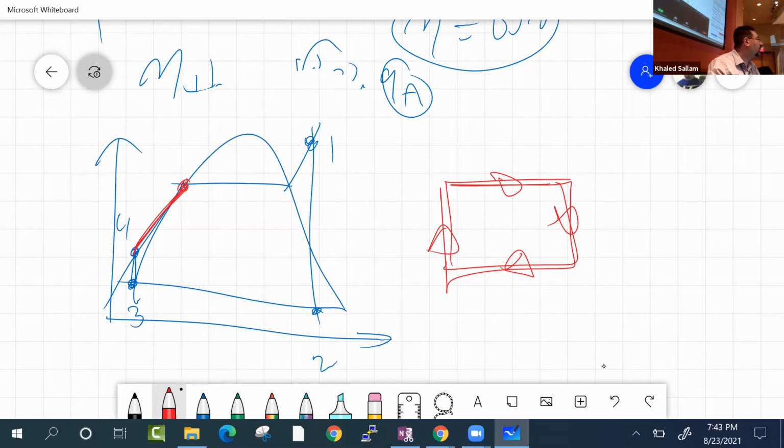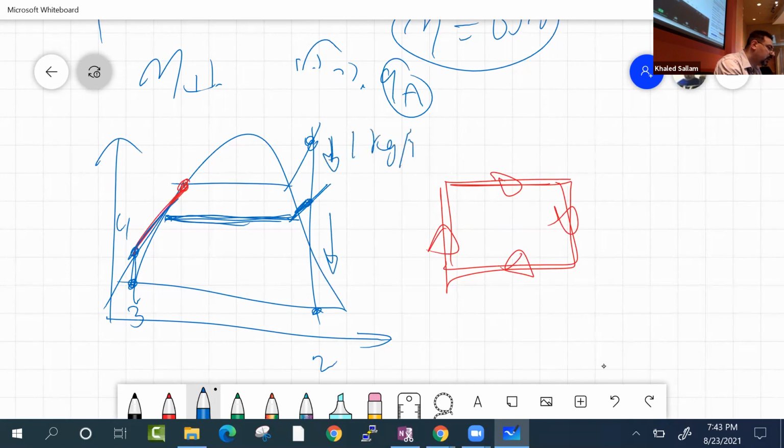So they figured out that I can heat this using that steam. I can take steam from here and send it over there. Yes, I will have less m dot going forward here. If what's coming here was 1 kilogram per second and you pull m dot here, then over here you have 1 minus m dot kilogram per second.